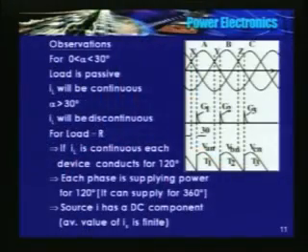I trigger T1, T2, T3 at alpha equal to 30 degrees. So where is alpha equal to 30 degrees? Any angle that is an integral multiple of 30 degrees, I can determine on this waveform, because at every 30 degrees either it will cut the x-axis or there is going to be an intersection. This is alpha equal to 0, that is the point of natural commutation.